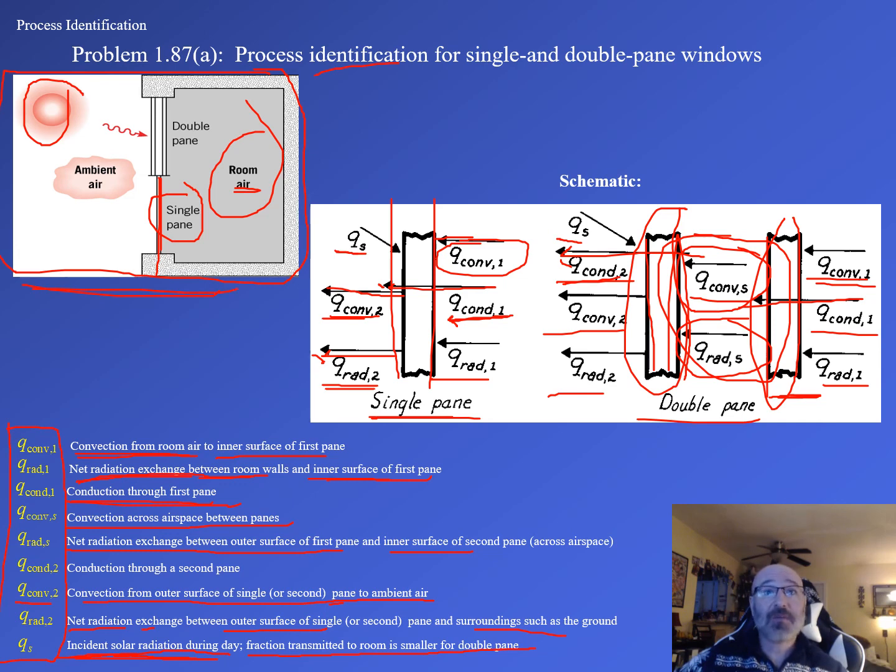So we have this here, but then we also have the schematic, which is very important. It can help us when we start plugging into our governing equations and need to understand, okay, how do convection, radiation, conduction for each of these surfaces relate? Where do they plug in with my indices and my variable names within my problem and my governing equations?